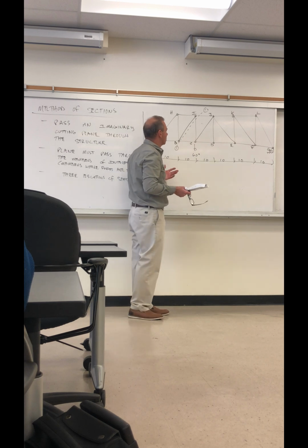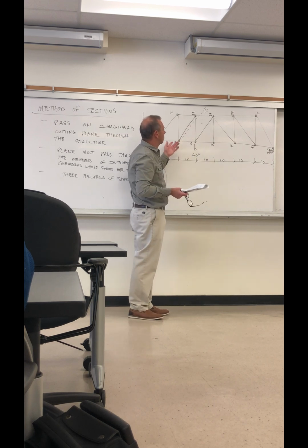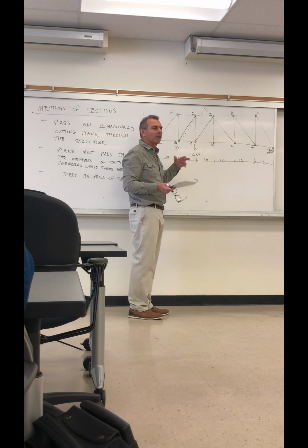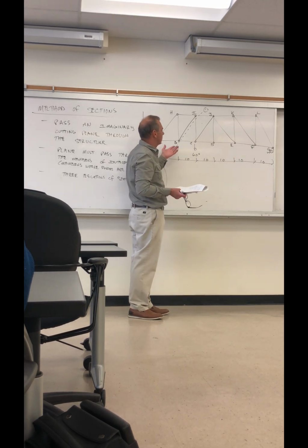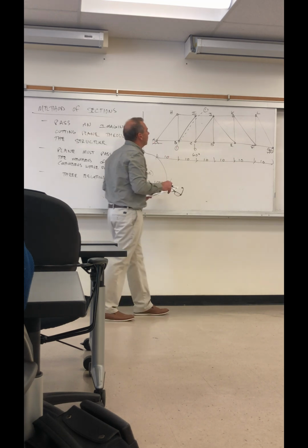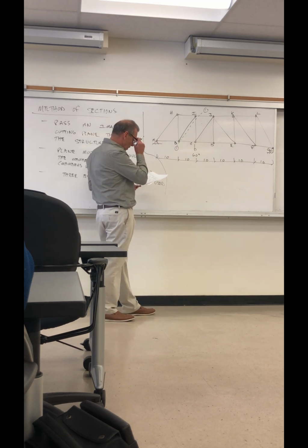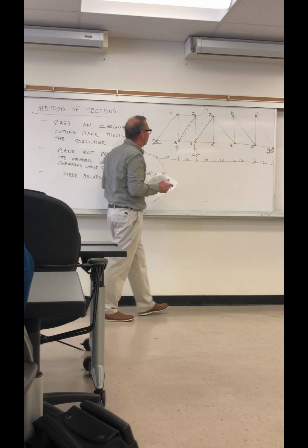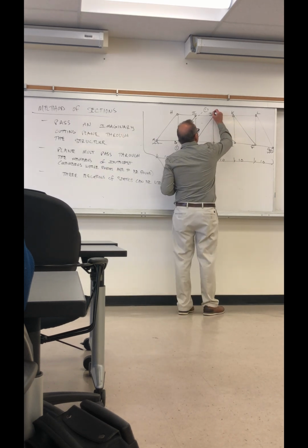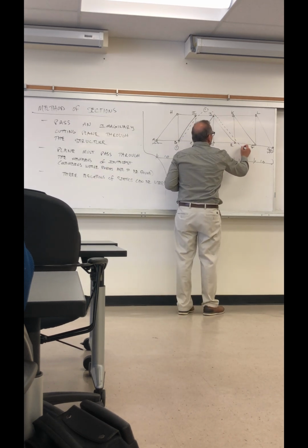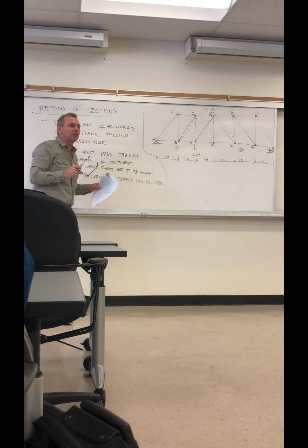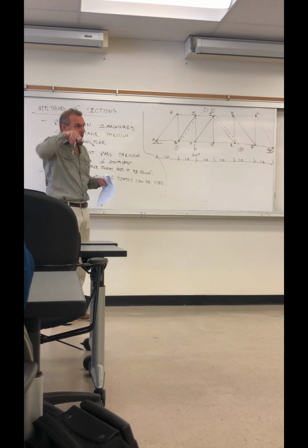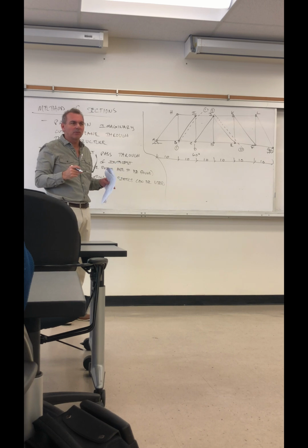So if the question was, what's the force in member IC? You could take this section cut and solve for it. Or if the question was, what's the force in BC? This would work, or IJ. So let's keep that in mind. Section 2-2 is just to the right of J and E. And then look at the members that I'm cutting through. These section cuts don't depend on each other, so I'm not doing them in any order. They're just different examples of section cuts.